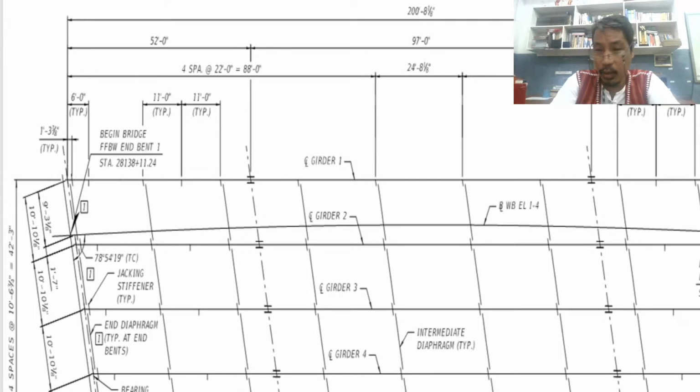Okay, 1.67 and 2. We already took note of that in our steel design. What about LRFD? What are the reduction factors in LRFD? I already showed you 0.9 and 0.75. Take note of those things. I already showed and explained those things.